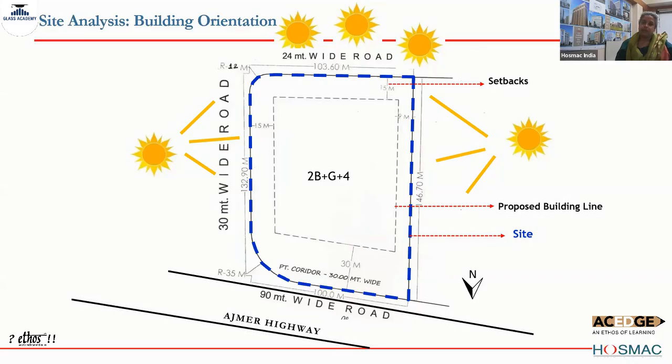We also need a facility mix before we start our program of designing the hospital, because we need to know how the building will sit, how many floors it will have, and how it will sit with respect to the composition of the departments which are going to fit into this hospital building. Now, a healthcare building will have a lot of departments, clinical and non-clinical, and administrative support areas which have to come in. So a facility mix is a program where we understand what goes into a hospital.